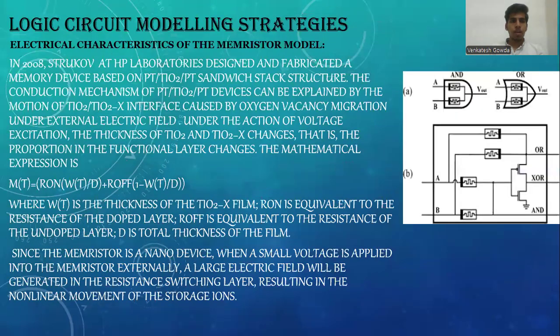Now we shall discuss the logic gate modeling strategies. In 2008, HP Laboratories designed and fabricated a memory device based on a Pt/TiO2/Pt sandwich stack structure. The conduction mechanism of Pt/TiO2/Pt devices can be explained by the motion of the TiO2/TiO2-x interface caused by oxygen vacancy migration under an external electric field. Under the action of voltage excitation, the thickness of TiO2 and TiO2-x changes, that is, the proportion in the functional layer